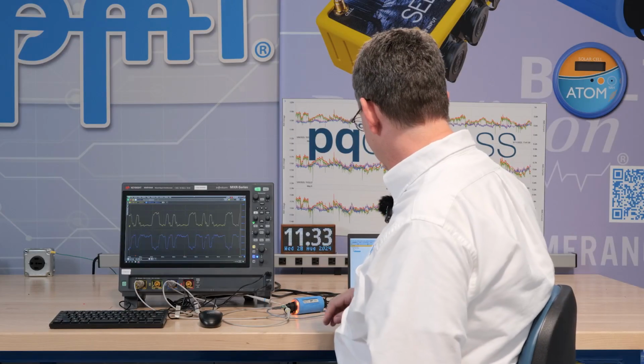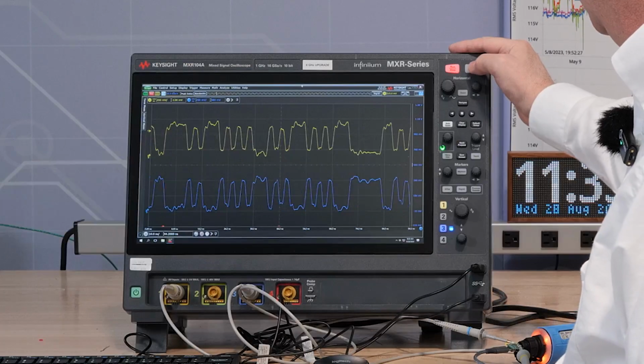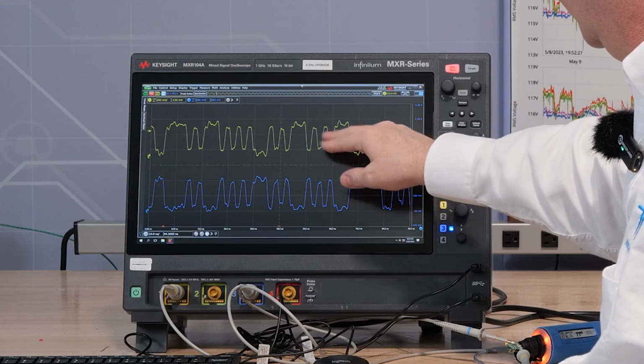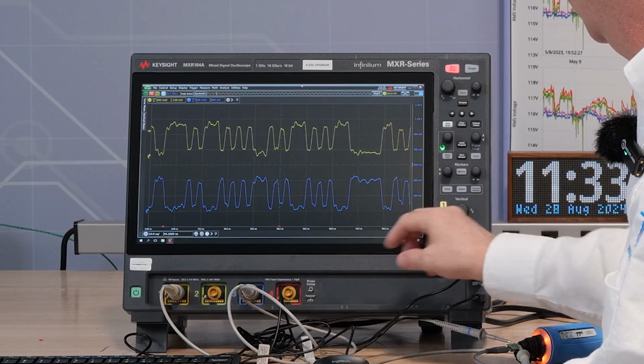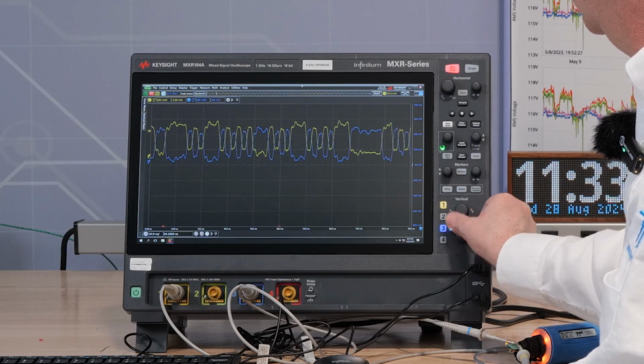And here we're doing a transfer now through ProVision to exercise data through the USB port. And if we look at individual traces, we have one scope probe on D plus, one on D minus. We can see that they are indeed differential. One is high, one is low, and vice versa. So to look at this in more detail, we're going to switch the scope into differential mode and take a look at the signal quality through an eye diagram. So let me switch to that mode now.